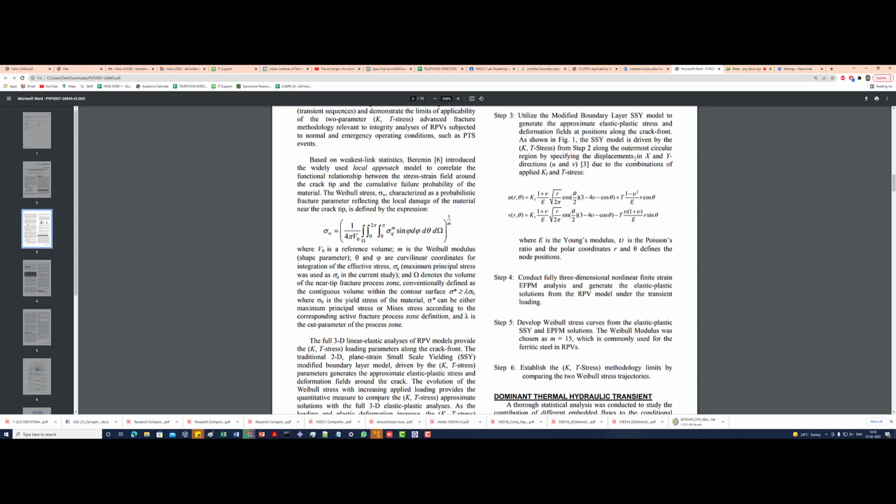So this is going to be your plastic zone radius, and then multiply this by 10 to find out how large a circle you have to take out. Is it clear? Okay. So once you have made this model, then you know this is the boundary condition you have to apply, and now we will see how we can apply these boundary conditions.